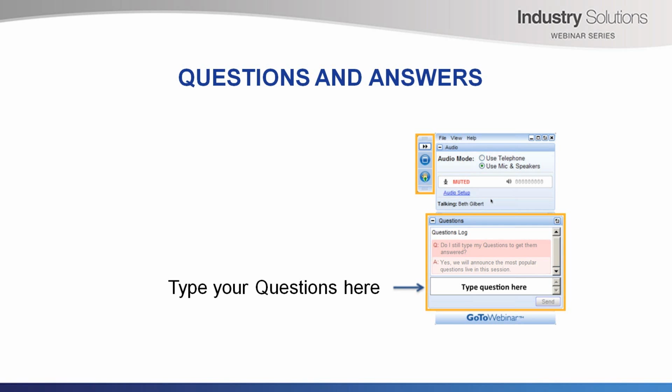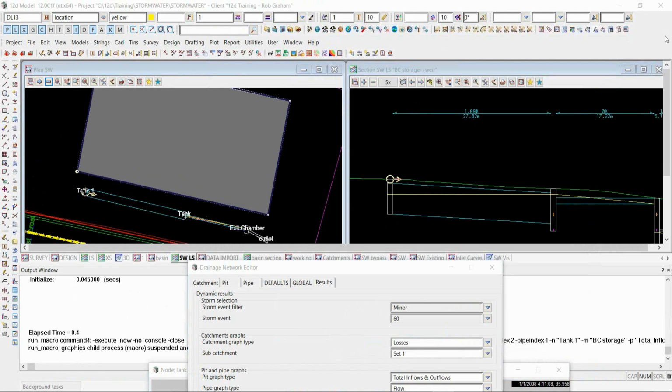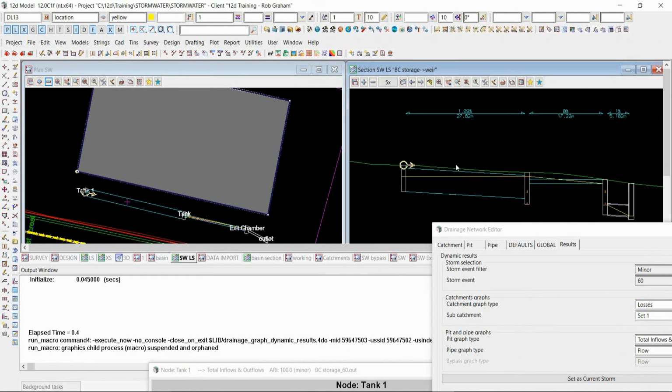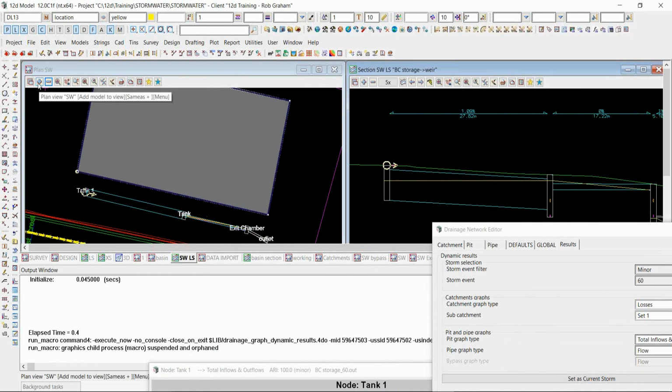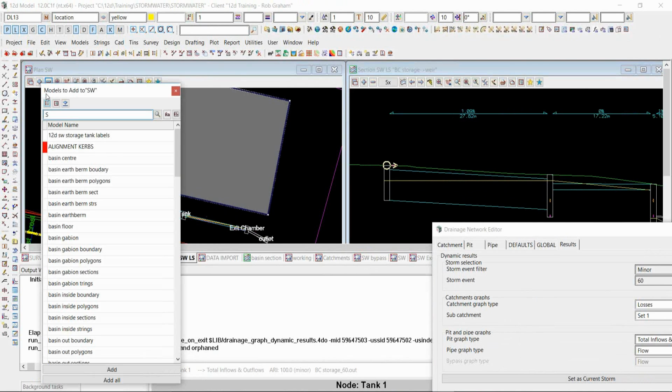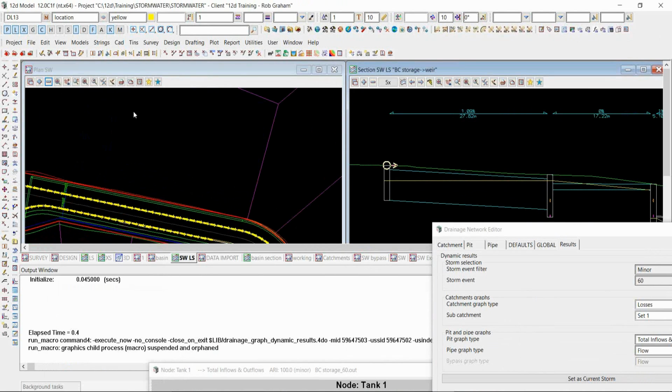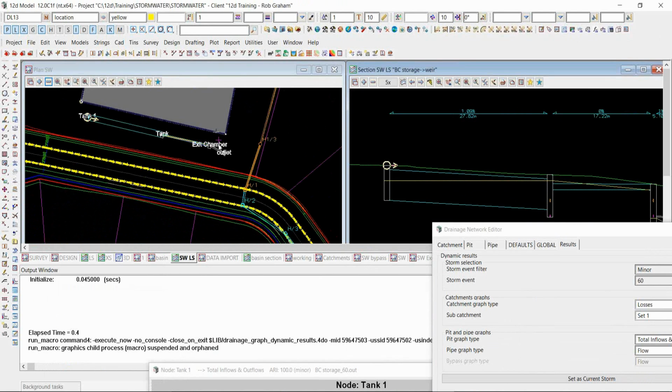Really good question, and absolutely yes. What I've done inside this presentation was just isolate a very small component. One of the things I was careful to do was make sure that we had no backwater controls while I was doing this. But if I was to put on the rest of my stormwater model for the whole project, the very next thing I would do is grab my outlet, drag and drop it into my stormwater network, and then it would become an integrated part of the entire stormwater network. So yes, to the first question, it can be part of the entire design, and it should be.